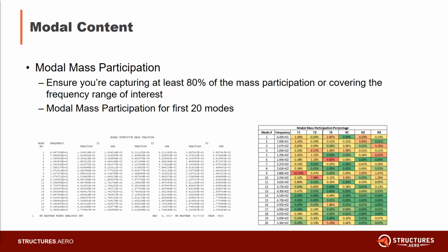One of the things we can immediately check is that if we know that we have a lot of energy occurring in some of these modes, we will probably see a lot of response at these locations. So for instance, maybe your input drive, or maybe something is driving the structure at 80 hertz, then we would expect to see a lot of response coming out of the direction for this mode 2. So again, always run your modes first to try and get an idea of the behavior of the system before you start running a full dynamic analysis.